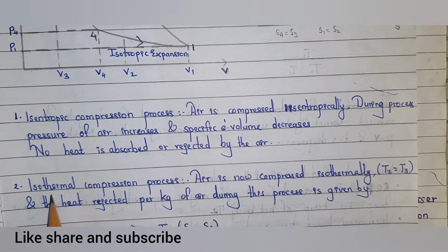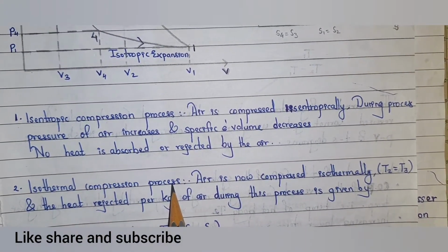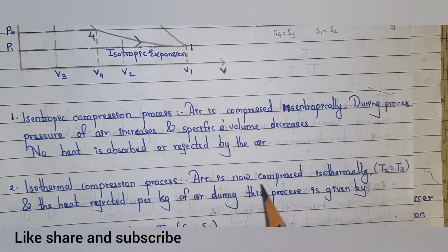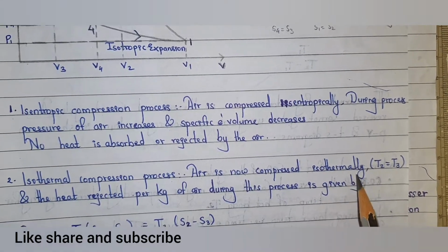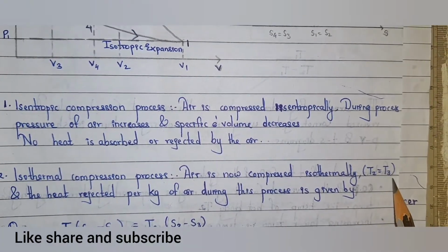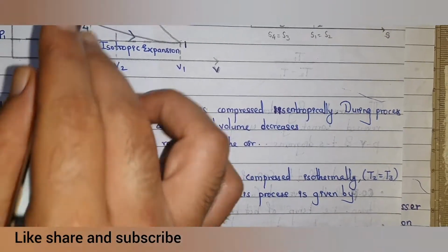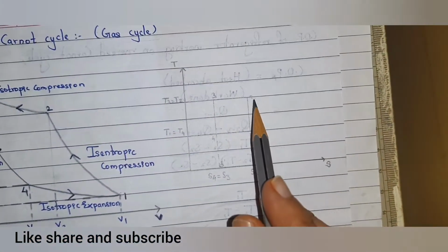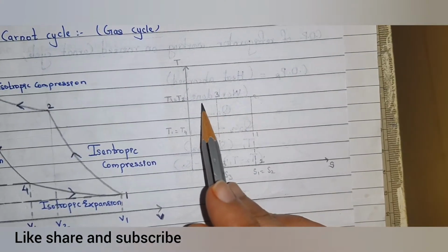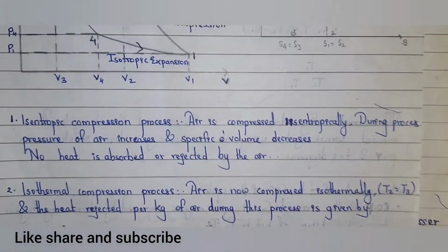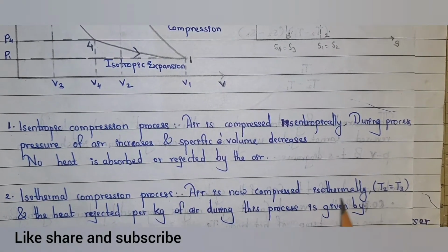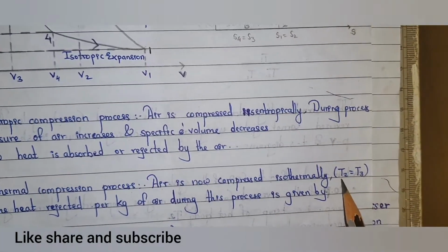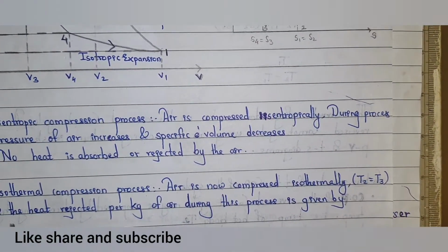Now our second process is the isothermal compression process. In this, air is compressed isothermally, that is T2 is equal to T3. This takes place from point number 2 to point number 3, as you can see in the figure. Now isothermal usually means at constant temperature. So here we are seeing that T2 is equal to T3.